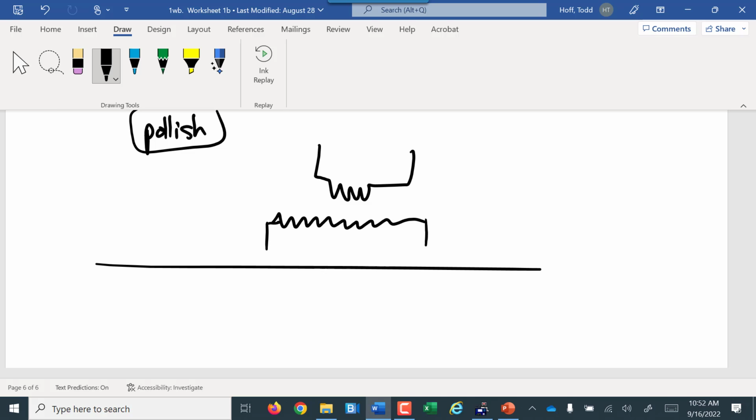Yes. Those either have to be lubricated so they're not dry, or you have to keep them moving, because once they stop, it takes a lot of force to get them going again. We have ceramic valves, like electronic controlled valves. You actually take them apart, and I tell you what, you just pop fingernails off trying to get them separated. And when those fail, it's usually not while they're moving. It's usually once they've stopped and they start moving again. That's usually the failure on those.